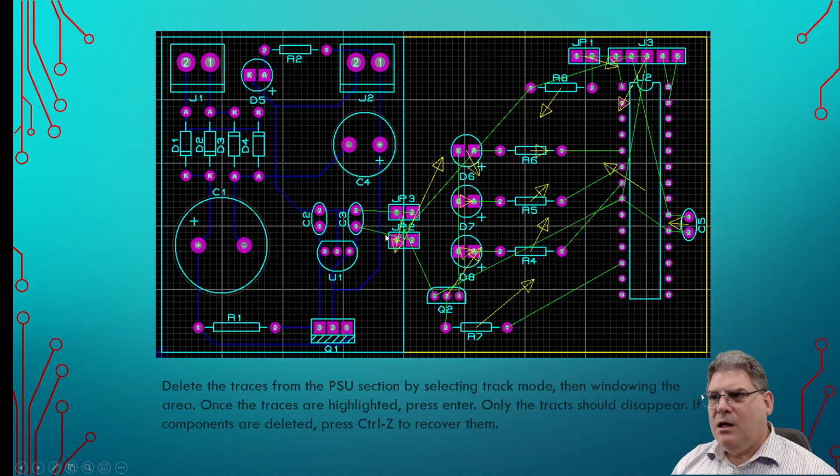All right. Okay, so take a few minutes. Place your components similar to this. They don't need to be exact. As a matter of fact, you can add your own little bit of flair at this point if you wish. But do keep in mind that we wanted to keep this capacitor as close to the microprocessor as possible. You definitely want the programming port and the reset jumper in a logical place, and try to lay out your parts so that the flow kind of makes sense.